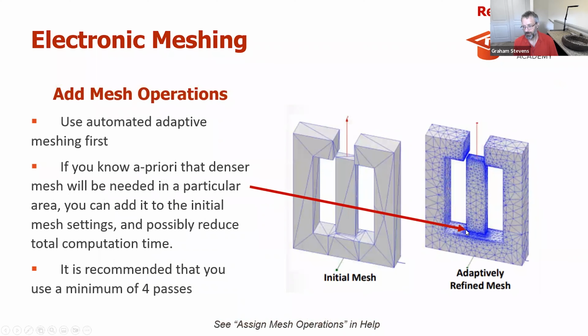So in this particular area, I have the arrow here where you have a lot of mesh points, and a priori, the magnetic gradient around there is going to be really high. And so you can finger those surfaces and create denser mesh in that area at the beginning. And by so doing, you can sometimes reduce the number of cycles that the mesher is using to converge and to do its automatic meshing.